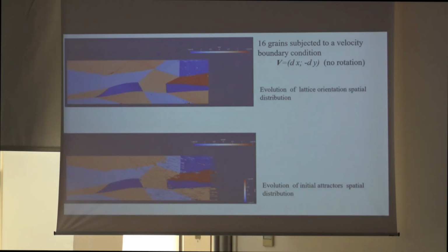It cannot be exactly like that because, as a matter of fact, we have supposed in all this theory that the strain rate is constant everywhere, which is not exactly what happens. We can impose the boundary condition, but the crystals after that have a different behavior and they have to manage the different orientations of the grains between them.